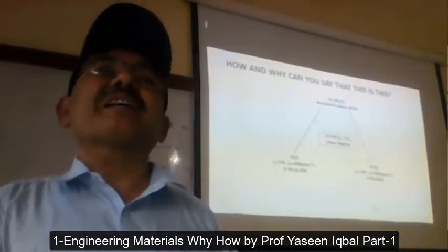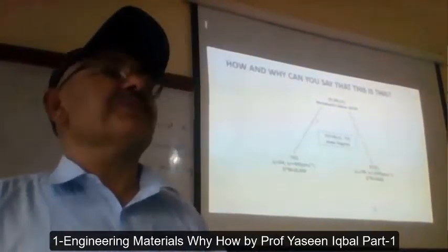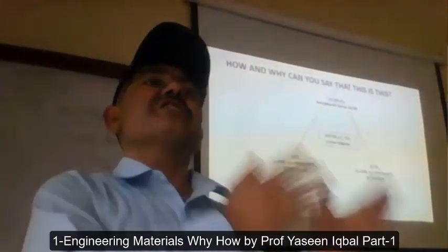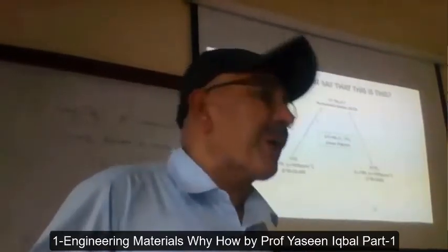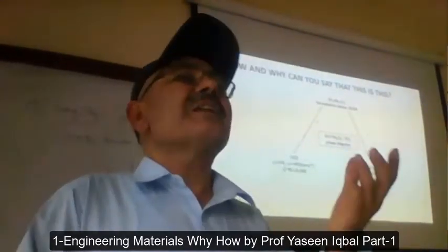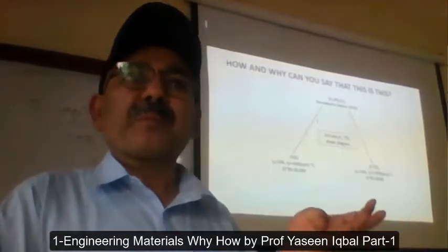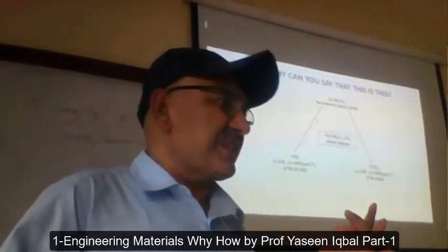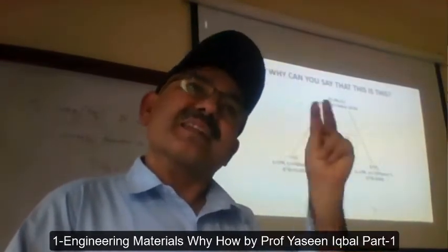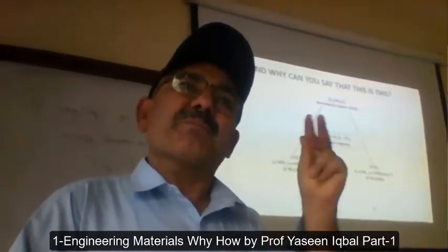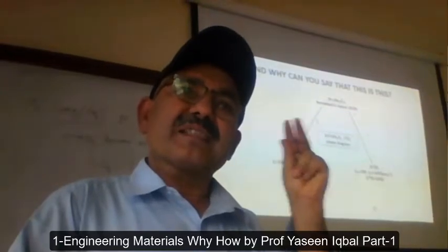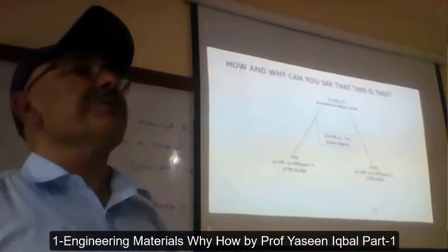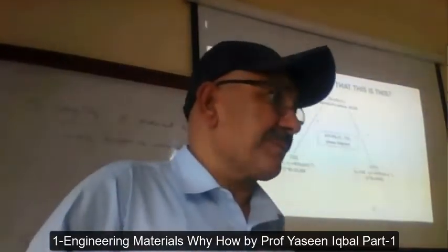Thirdly, its weight is not that much, so that when you consume petrol or diesel or whatever, it is not totally consumed to carry the weight of the car. So this means you need lightweight, excellent mechanical properties, and heat resistant material. You got these three, the set of properties. This is a set of three properties for body material. Now you engineer material for it.